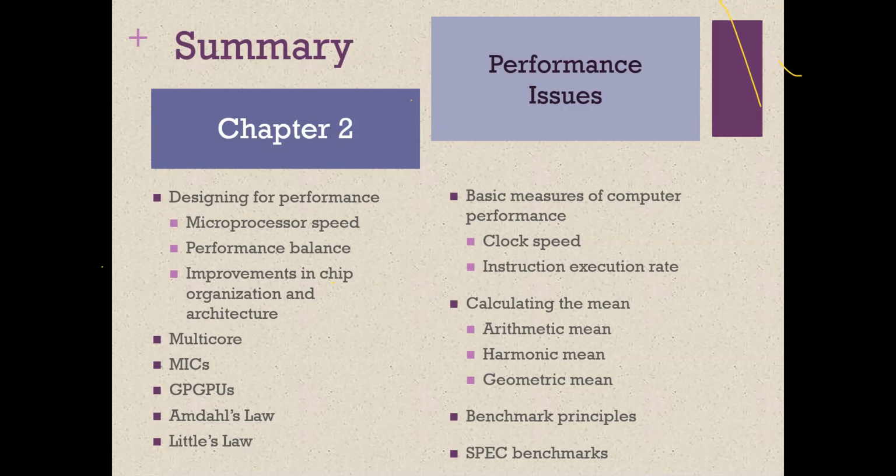If there is, it will deal with that like a loopback or a feedback. And so then that interrupt request is now going to be fetched within the fetch cycle, and then executed within the execution cycle, and then it goes back to check again on the interrupt, and so on and so forth. So that redefines the instruction cycle for us. So when we talk about the stages, that's what we mean.